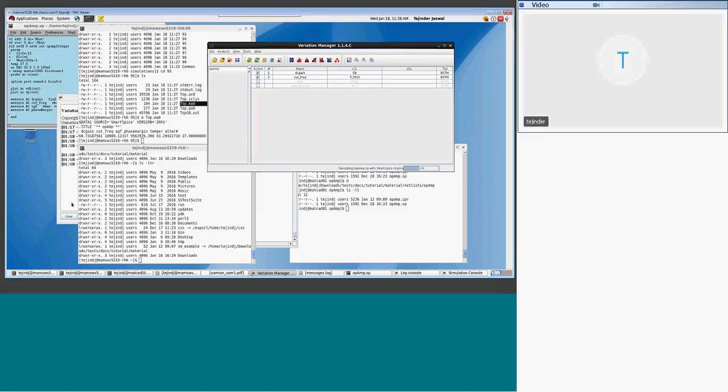For example, if fast Monte Carlo terminates with 400, then you go for 5,000, and it will use the first 400 and maybe add new simulations, 30 or 40. So it's incremental, and the more Monte Carlo requested, the more speed up the tool will give you. For sure, more Monte Carlo is more accurate.